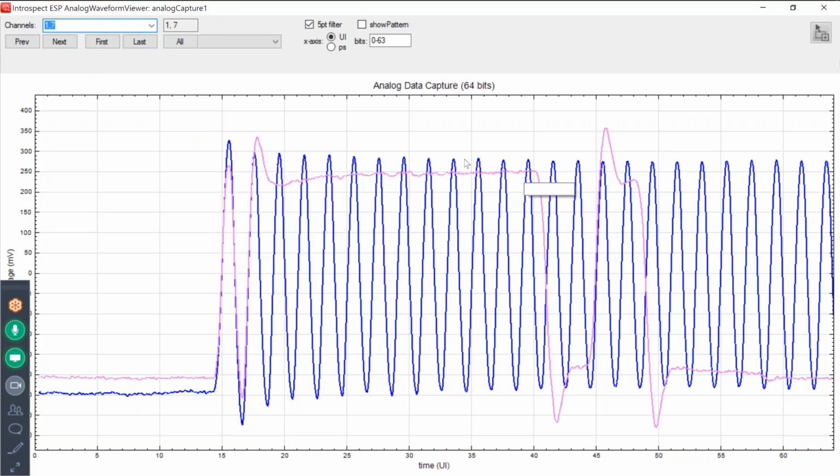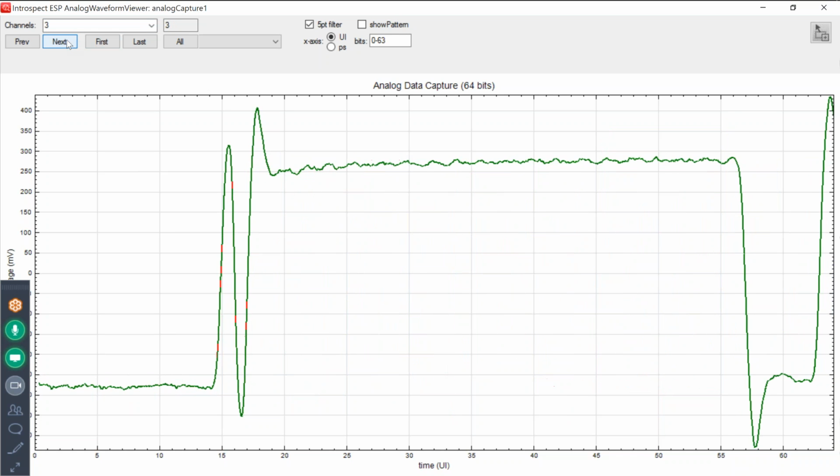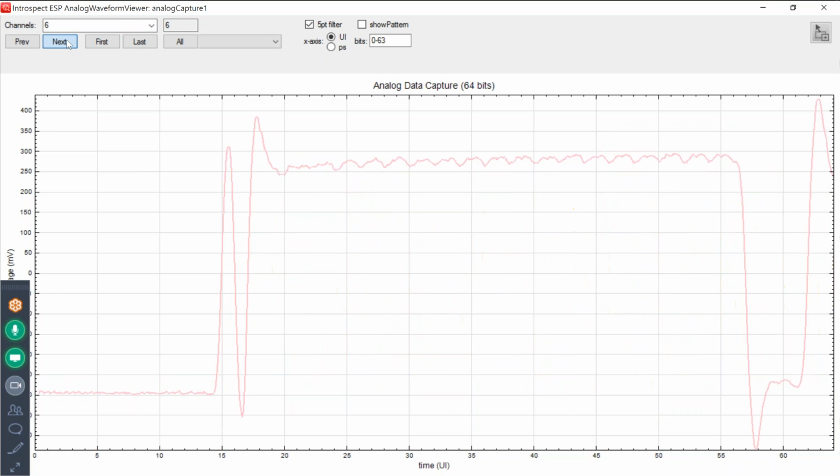Another measurement point that's typical could be the high-end point here on the pink graph, where again, instead of measuring at the sequence of long zeros, we measure after a sequence of long ones. And so this is just a quick illustration to show how we could trigger each channel really to be independent of the others and still capture the waveform patterns progressively this way. So each channel now is triggering on its own window.